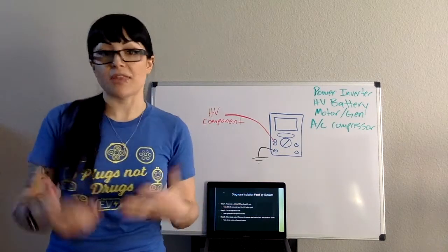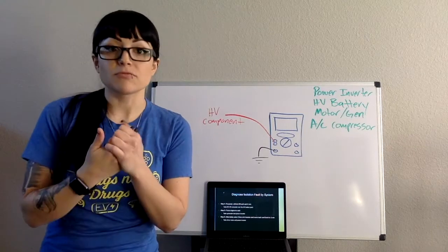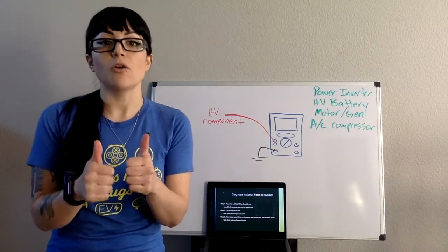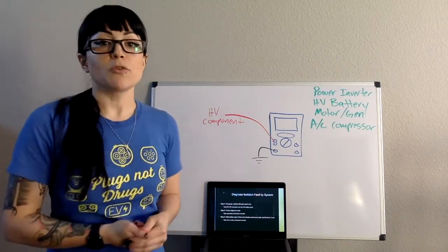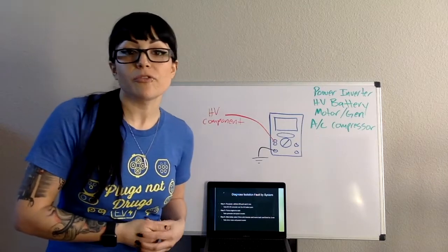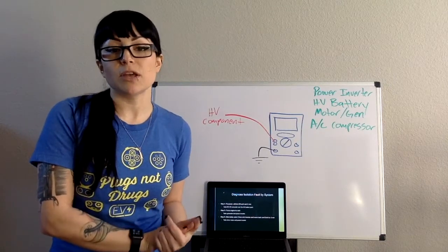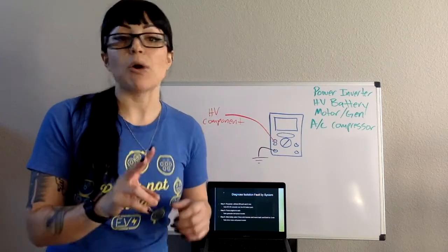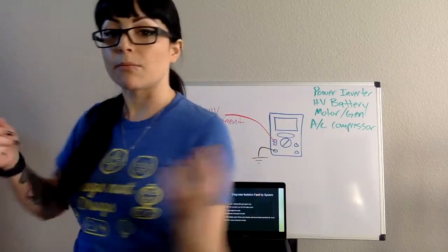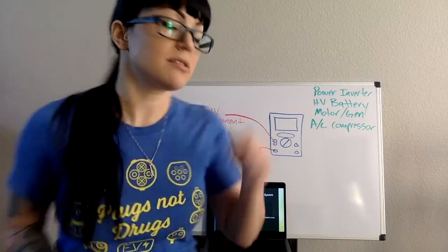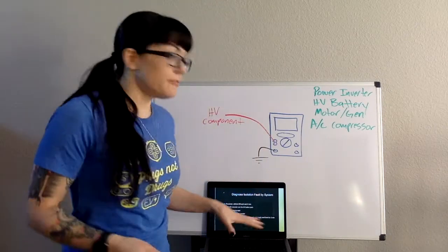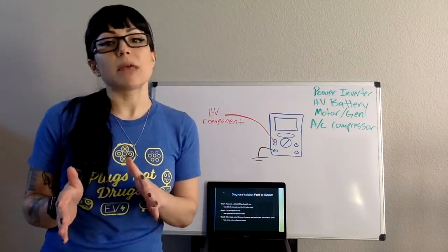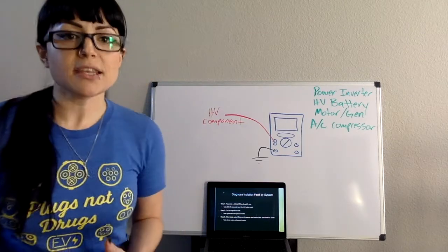Or another thing that is up and ready to go as soon as we power on is our high voltage battery pack. So if I get an isolation fault in that first 2 minutes of turning the vehicle on, it is going to be one of those 2 components. And now I know I'm going to take my insulation meter and test those 2 components. Step 5 says, if I did not get a MIL yet, the next thing to do is to